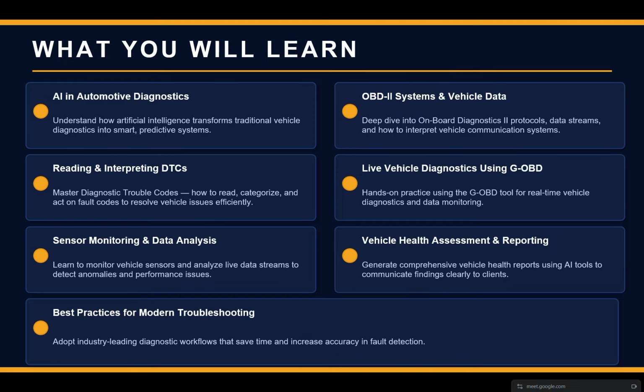Then you analyze all of them together and say, okay, this is what is responsible for that fault. So it takes a lot of time. With the fault code, it's easy because you can just go through the fault code. But when you start analyzing live data, you have this fault code, several sensors could be the cause, and you want to analyze the live data.